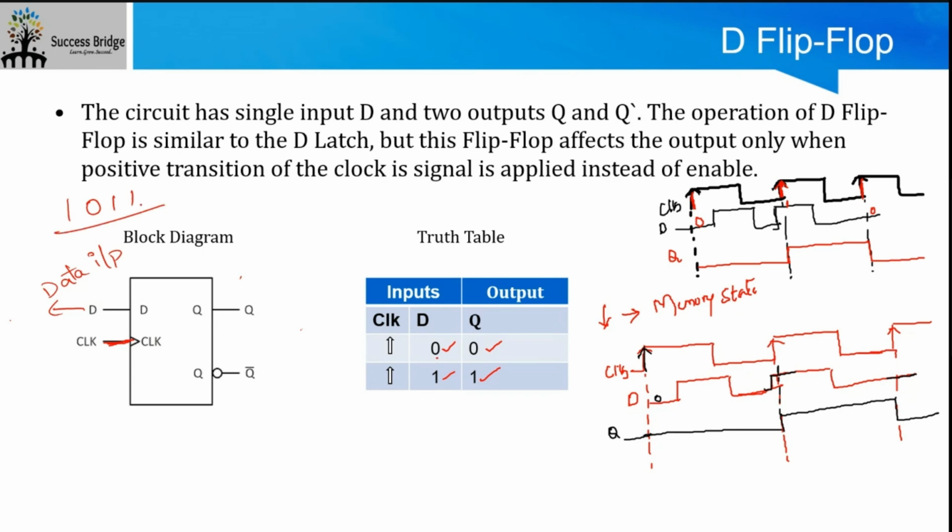But this is 4 bits of data, and you have only one flip-flop. To load 4 bits of data, you need 4 flops. Remember that each flop can store only 1 bit of data at a time, at a time meaning on that particular cycle.